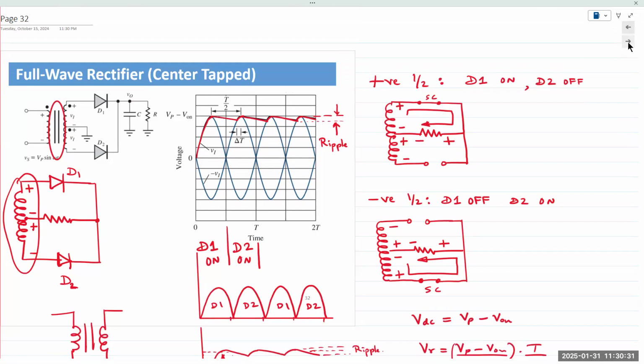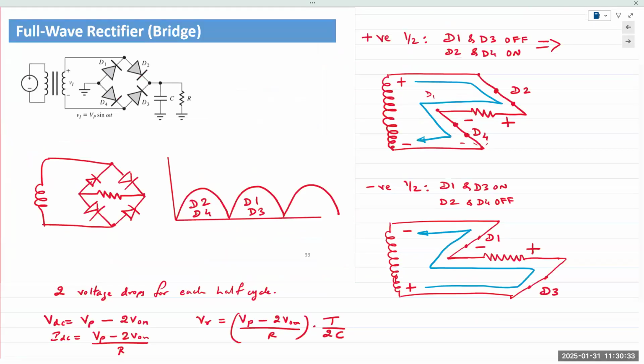So create another circuit called a bridge rectifier. This is by far the most common one. You have 4 diodes connected in a bridge configuration. And these 4 diodes are connected again to an AC input. In this case, the transformer is nothing special, just a simple step down transformer, depending on our output requirements. And you connect a load resistor.